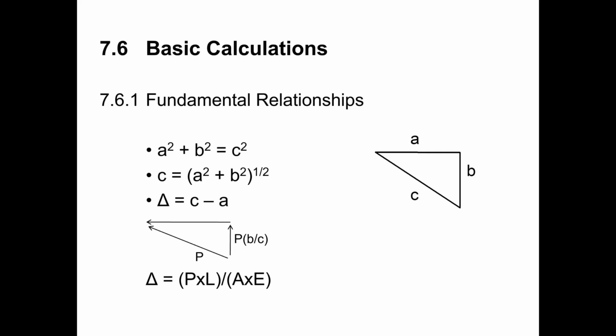So if you just think about these hold up devices and hold down devices, as the strand changes direction, as it goes from horizontal to a diagonal, there's going to be a vertical force that occurs at these locations. And so we need to be able to calculate what that vertical force is so that we can make sure that our hold up and hold down devices have adequate capacity, and also so that we can make sure that whatever our hold up and hold down devices are connected to have adequate capacity.